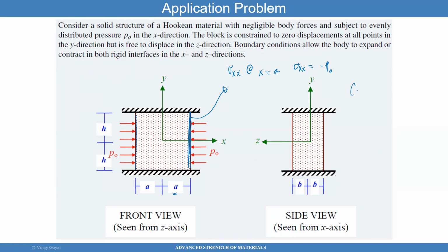So what does Cauchy's formula say? Cauchy says that on the surface of the body, the traction is T1, T2, T3, or we can use letters like we've been doing here, X, Y, Z. And I have the stress field here. On that surface, I know the normal, nx, ny, and nz.